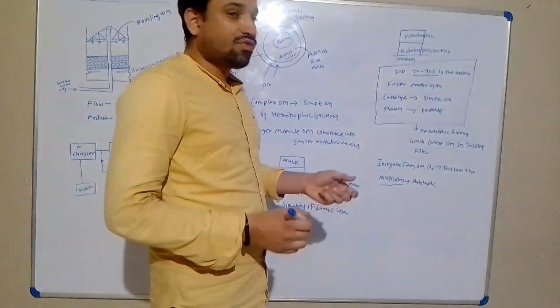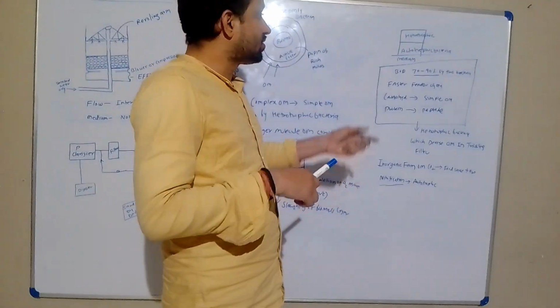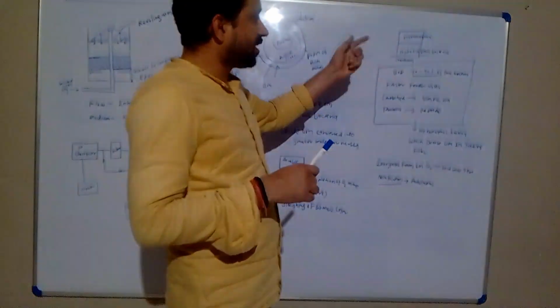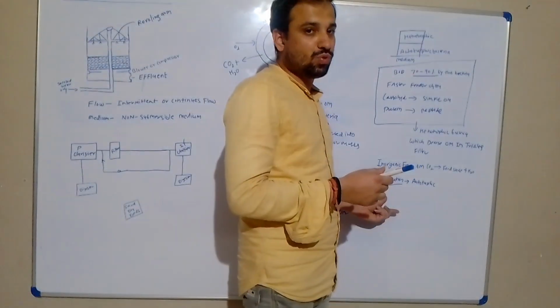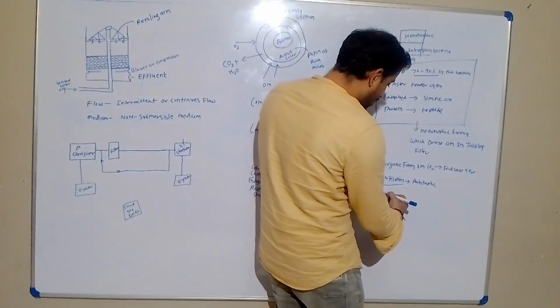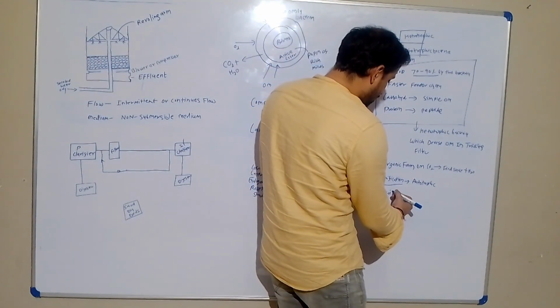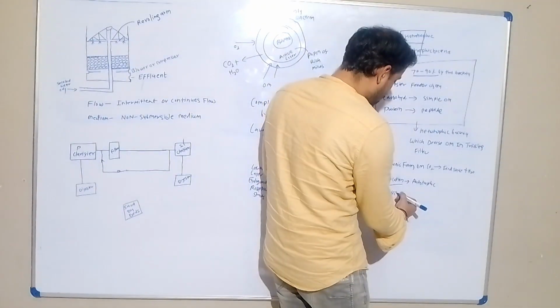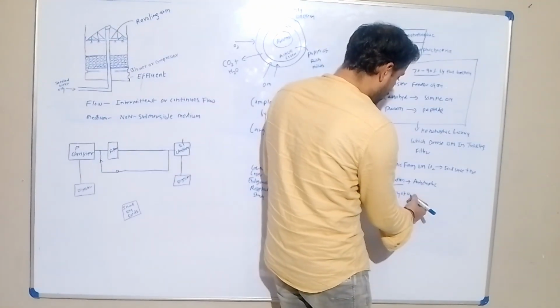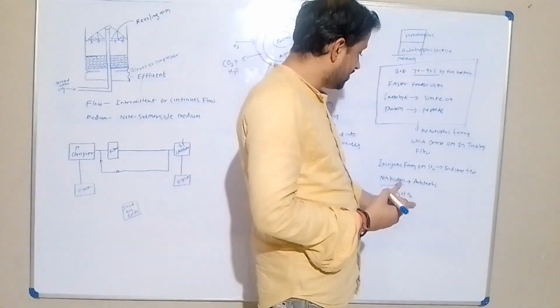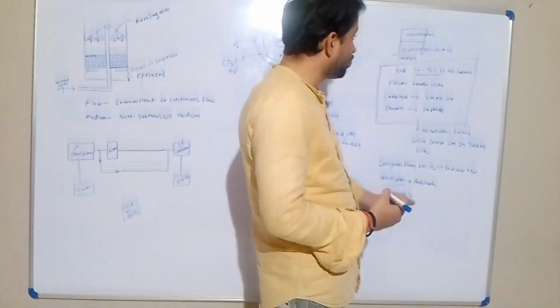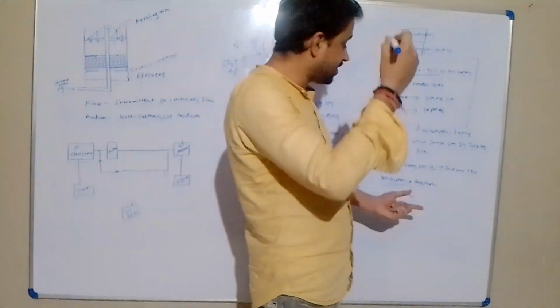The ionic form of oxygen in the wastewater is utilized directly by these autotrophic bacteria. There is a decrease in O2, and the availability of O2 is restricted here. This is the restricted zone in the biomass layer.